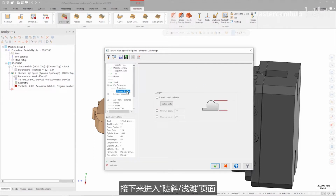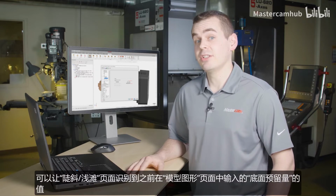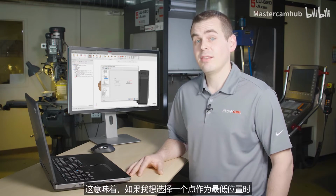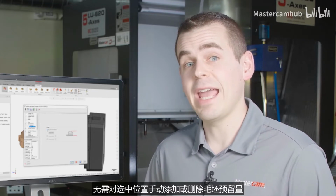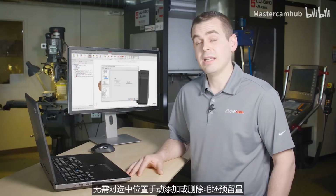Next, we'll go to the Steep Shallow page to look at another new feature for Mastercam 2020, Adjust for Stock to Leave. This new option makes the Steep Shallow page aware of the floor stock you entered on the model geometry page. This means that in a situation where I want to select a point for my maximum depth, I don't need to remember to manually add or remove my stock to leave amount from the selection I just made. Instead, Mastercam will automatically apply the stock to leave value I entered on the model geometry page to my minimum